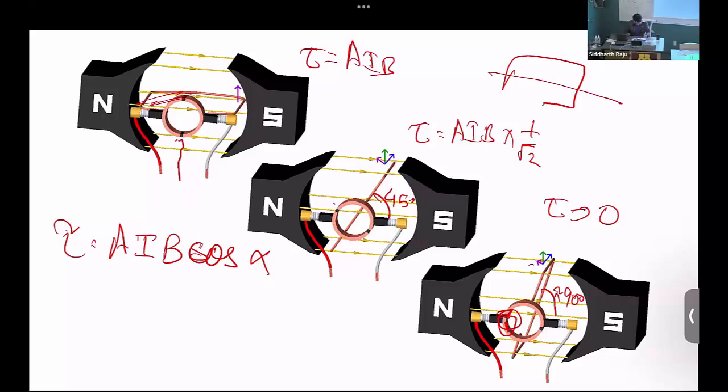This black thing that you see there is typically mica material. The orange things are the copper segments, and in between the two copper segments they are isolated using mica, which is a very good insulator. But if your brush is much smaller than the thickness of the mica, then there is going to be a time when the top copper ring and bottom copper ring are not going to make any contact with the external world.